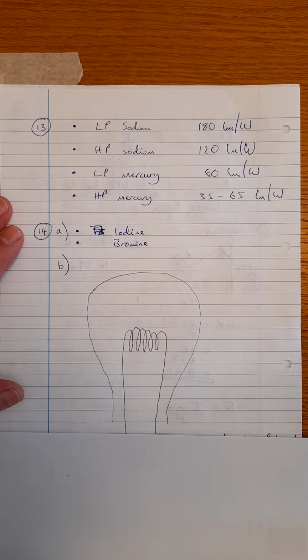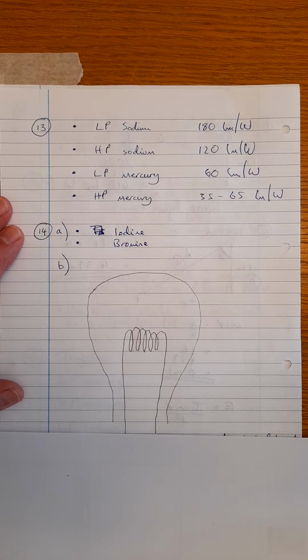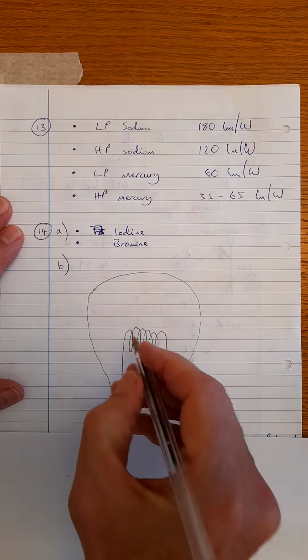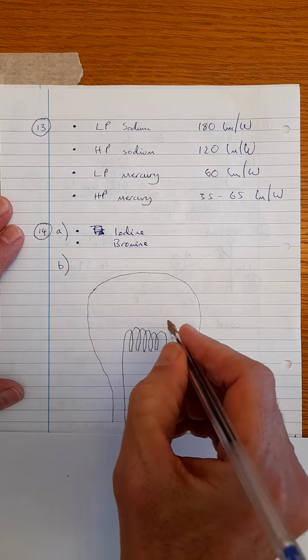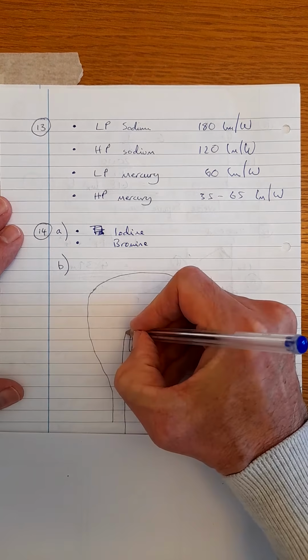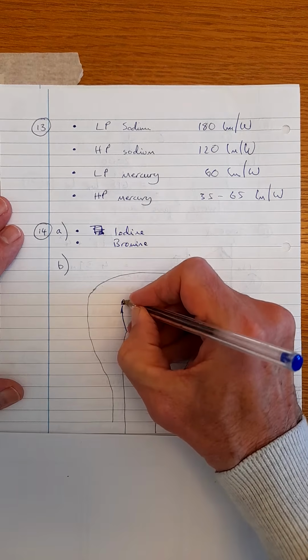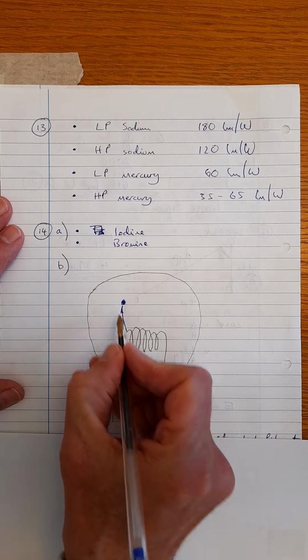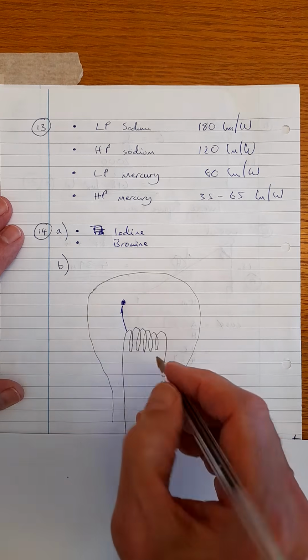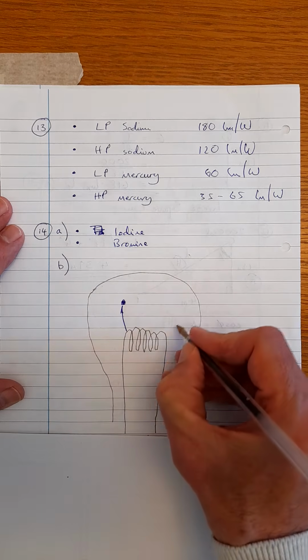Okay, so let's have a look. I've got an outer glass bulb and I've drawn a really naff little filament, but it doesn't matter. If I remind you about the process that we're going to talk about, then what happens is when we heat this filament, a particle of tungsten is going to leave. So a particle of tungsten will leave that filament. And with the halogen cycle, it's eventually going to come around back to here.